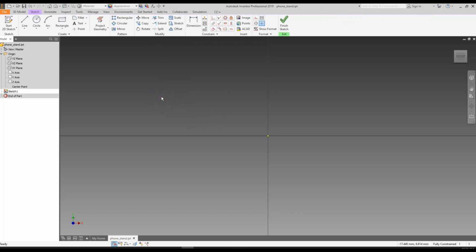So the way sketching works in Inventor, the way you really should work the sketches, is that you first rough sketch approximately the shape you want, but you don't worry too much about the exact dimensions in the very first step. So let's just sketch it for approximately the shape we want. To make this cross section that's a box with a rounded end, I'm going to pick a line tool, and then I want to start in the origin.